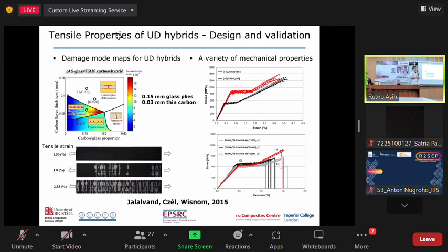High strength and high modulus carbon. I think it's kind of graphene carbon. It's a continuous carbon fiber. So it's fiber prepreg. It's like a sheet. So we just add it on top of each other and then we cure it inside the autoclave with a curing temperature of 125. But I think at least it's kind of a graphite. It's called the high modulus.